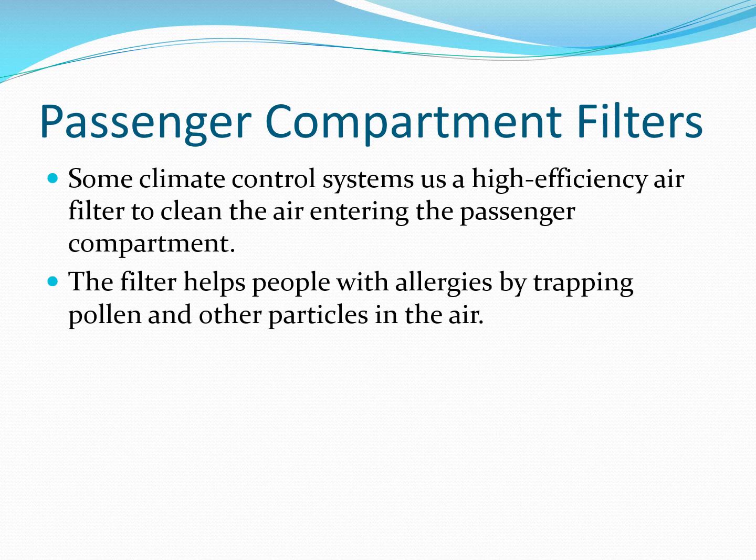I've even pulled some out of vehicles that actually have small little plants growing in the filter. And that's from tree seeds or plant seeds coming through that grill work. Add in dirt, add in moisture from the air, and you've got a perfect climate to start growing plants. And I have pulled these out that have little sprouts that have come out of that filter. That is well overdue. But if you have a vehicle that has these passenger compartment filters, it's important to change them on a regular basis, or at least check them on a regular basis. And that might involve pulling the glove box door down and pulling it out, or in some cases this is pulled out on the engine compartment side, and they'll have a little trap door that you fold down and change it out from there.